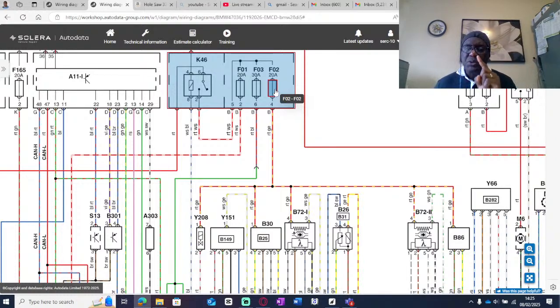It could be a power that is shared. One thing that I want you to take away with you today, or any other day that you access this video, is that you can't share a signal wire. Let me say that again. You cannot share a signal wire. You guys were in my class. I've told you level 3s, level 2s, especially level 3s, you will not have a signal wire shared with anything, but you can have a power shared as we have seen here, and you can also have a ground that is shared.